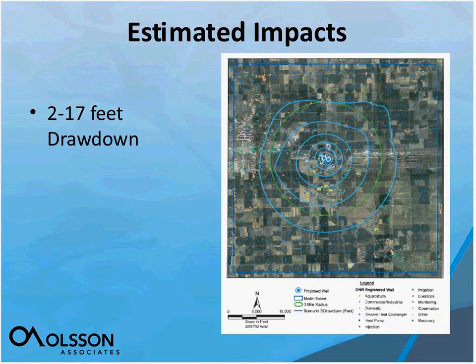The good news was the 17-foot drawdown was just immediately around those 2 wells, and they were wells that were going to be utilized by the power plant themselves. They can use different water sources too. So those 2 wells that showed a 17-foot drawdown were not going to be an issue.